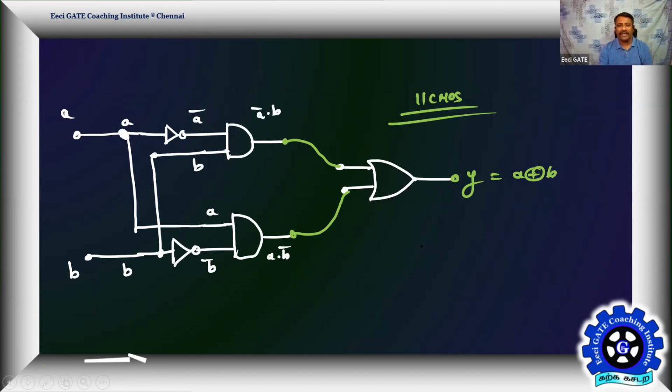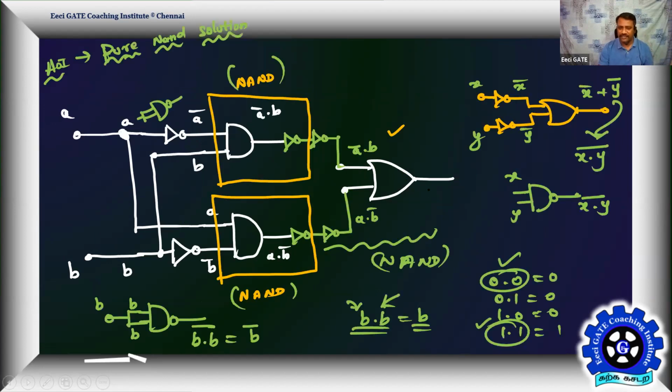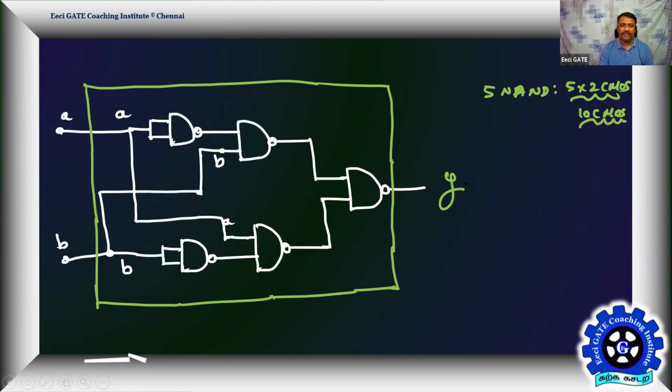If you go by AOI, it is in fact even costlier in the laboratory, because you'll be demanding an AND IC, a NOT IC, and an OR IC. One of each is enough, but that is a costly implementation of this exclusive OR function. The intelligent student will demand only two NAND ICs and implement the function XOR.